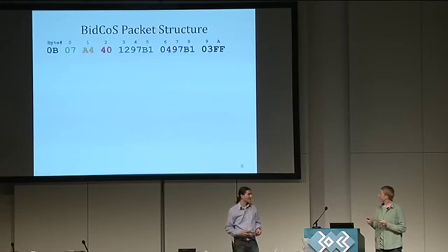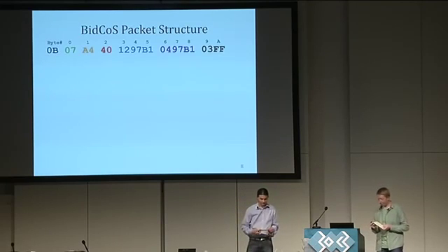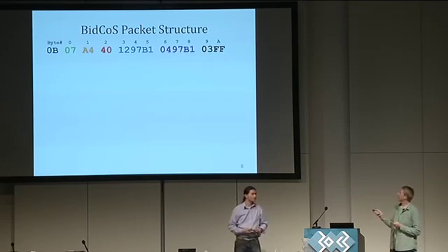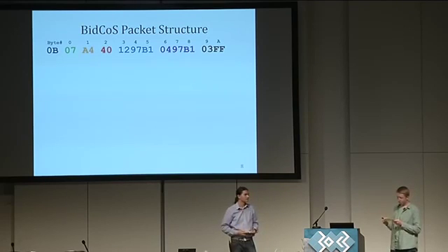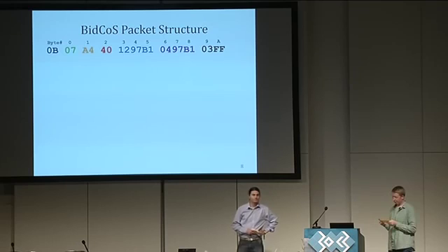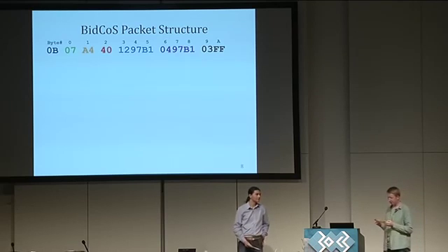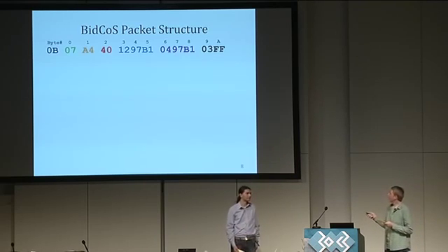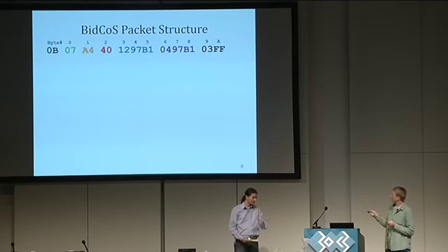Okay, the wireless packets. The protocol used by the HomeMatic devices is called BidCoS, which stands for Bidirectional Communication Standard, and works on a frequency of 868 megahertz, as a lot of wireless home automation systems. And all the BidCoS packets look like this.